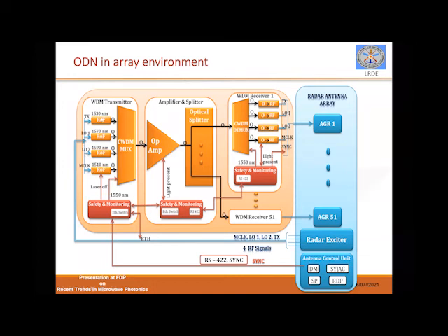Then please have a look here. All these are converted to different wavelengths. And again, here also the CWDM mux is used. Now you will be wondering what is this CWDM? This is coarse WDM mux, where, as I told you, there is a technology through which, over a single fiber, we can transmit multiple wavelengths. And there is one more terminology, dense WDM, that is DWDM.